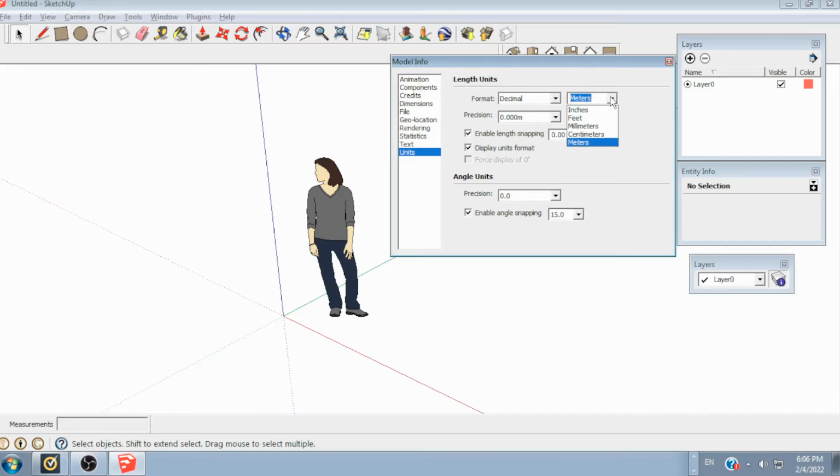It's meters by default. I usually prefer to work in either inches or millimeters. I'll select inches here. The resolution or precision shows 3 decimal places. That goes out to 1,000ths of an inch in the measurements that they do in boxes down there.